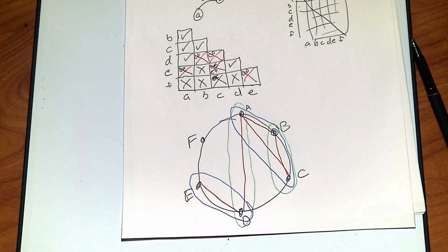Asynchronous is the devil in the details, because any small thing can screw it up. Each step is not horribly complicated if you realize the problems that can happen. You don't want glitches, you don't want races, particularly critical races. Glitches I can remove with K-maps, problem solved, don't worry about it. Just do K-map design or Quine-McCluskey, which is the equivalent, and we've seen there are fast ways to do that.